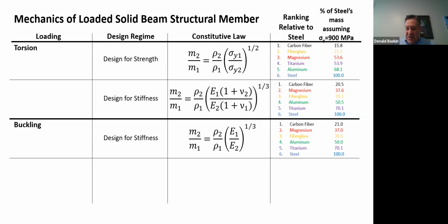But keep this in mind, that the stiffness isn't changing. So the stiffness, for example, of a bicycle frame made from commercially pure titanium versus 6-4 titanium will be exactly the same. If you have a titanium bicycle frame and you never plan on crashing and you just want a stiff frame, you'll get the same performance out of a relatively inexpensive commercially pure titanium frame as you would out of a 6-4 titanium frame. But the difference comes when you crash or your bike hits a telephone pole by leaning in the wrong way. You need that strength to stop the top tube from denting, because you need that off-axis loading strength.